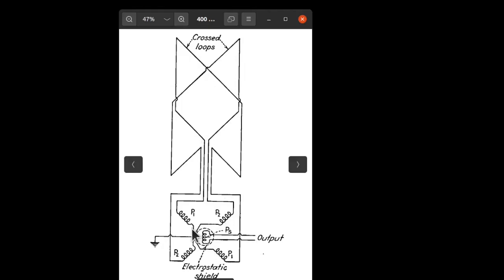If I turn this 90 degrees such that it's aligned in this axial, still causing all these coils to have induced currents from this rotor, then our field of sensitivity is in this direction, so 90 degrees.